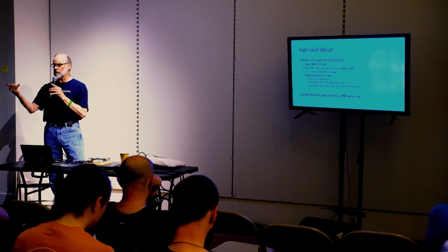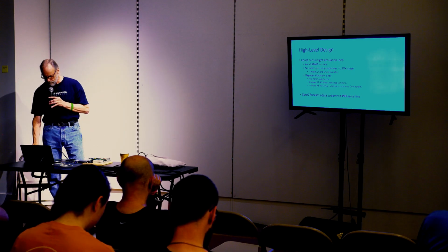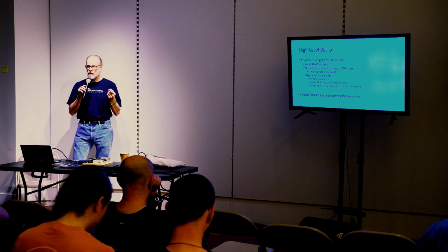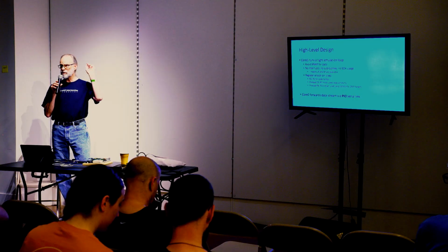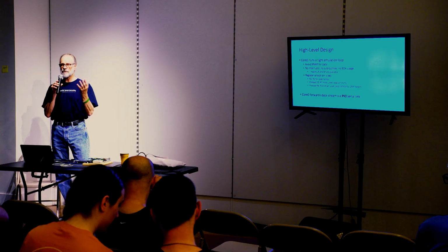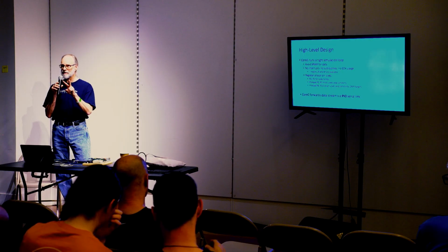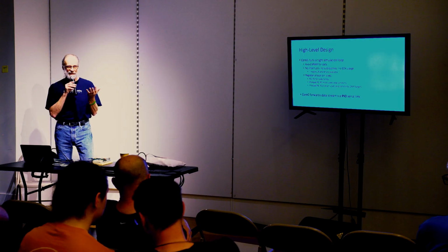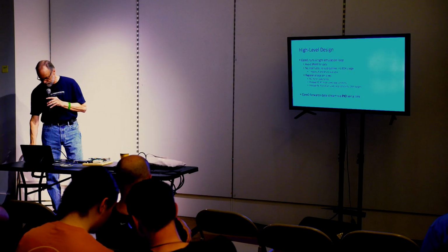They're just sitting there in registers, and I can just go bang and do what I need to do. In Core 0, all it does is take this data stream that's coming out and forward it to the other processor. So it's totally wasted. But the problem was I only had 2 spare I/O pins, and so really all it can do is send data somewhere else. So that's what it did.